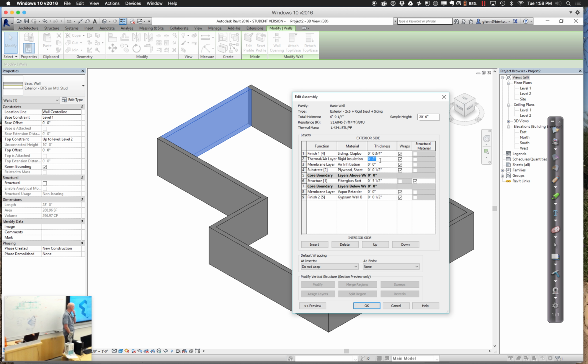R13 insulation. The way it works is typically fiberglass mat insulation, if it's 3.5 inches thick, is R13. If it's 5.5 inches thick, it's R19. You can think of those numbers as being very directly related to how much heat flows through. So an R19 wall allows for 13 over 19, that ratio of the energy, to pass through. So R19 really is quite a bit better. So having an R51 wall is actually quite good. It's quite a bit better than the walls in most of our homes.